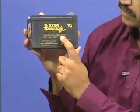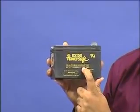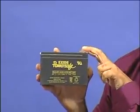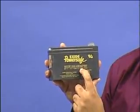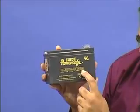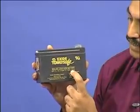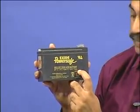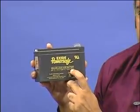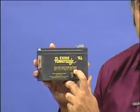Two of the most important things that you will have to see in the case of the battery is the terminal voltage. You will see that it is 12 volts, that is across these terminals. This is the nominal DC voltage that you would get across these two terminals. And next to it there is something else written called 7AH. It means 7 ampere hours, which means you could draw 7 amps for 1 hour, but in actual practice you can't do that, but that's what it would imply.